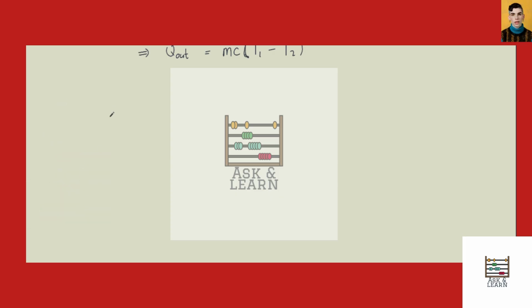Now the first thing we do is calculate the mass of one ball bearing and then the total heat transfer from a single ball bearing. So the mass of one ball is its density times its volume, rho times V. So that's rho times 4/3 pi r cubed, which is the volume of a sphere. But we have the diameter, so we can write it as pi d cubed by 6.